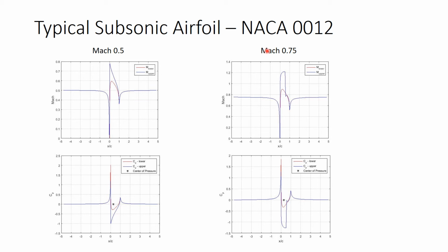And when this discontinuity can move around a lot on the surface of the wing, we wind up getting large changes in the moment that's applied about the CG of the aircraft. So ideally, we would like this shock to just occur in one location, if it has to occur at all, so that way we have a constant moment applied about the CG of the aircraft.